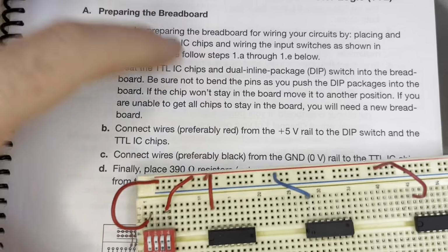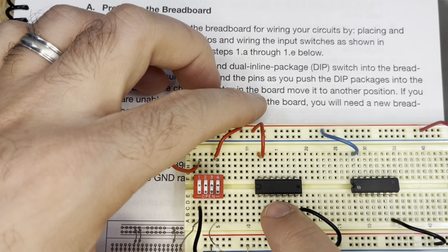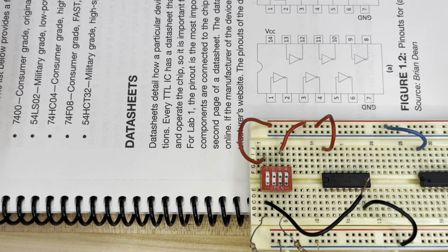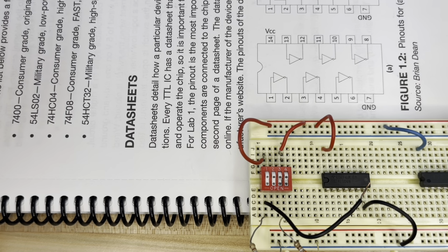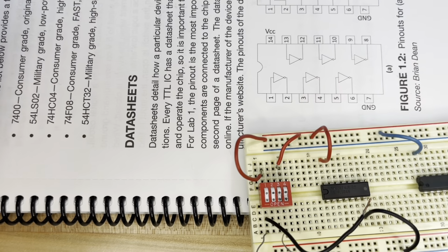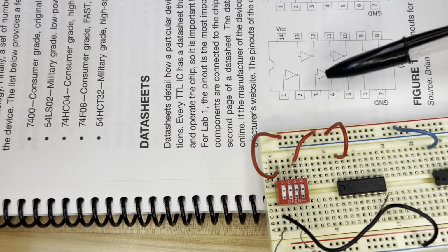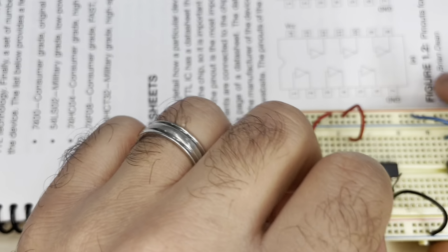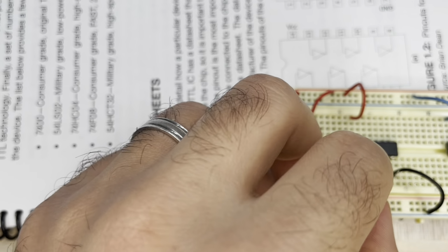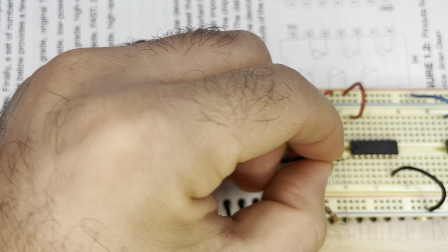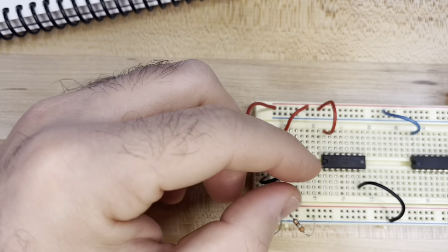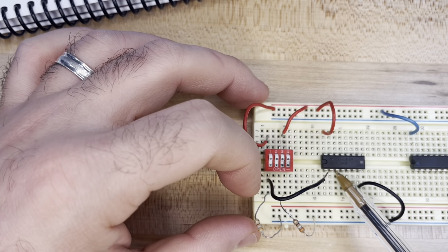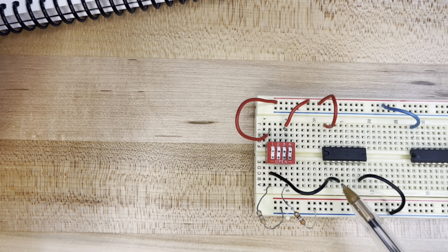So I go to the datasheet also of this exact IC after I determine it, to check where is the inputs and the outputs and pick a gate. Here I'm gonna use the second one, so pin 3 is an input, pin 4 gonna be the output. So that needs to connect to pin number 3. Came here and then I count them. So here pin number 1 is pin number 1, 2, so it needs to go to 3.